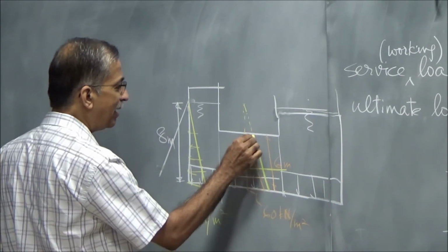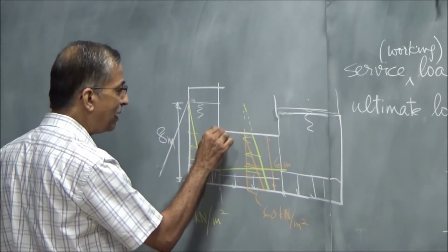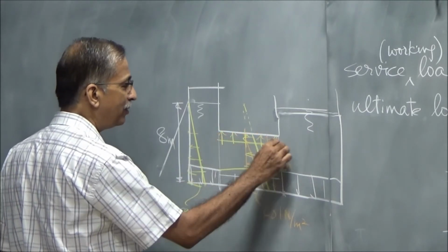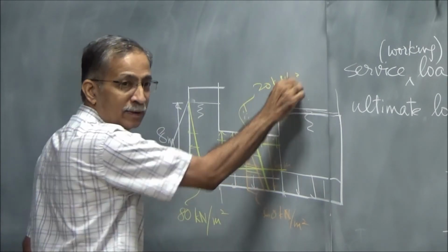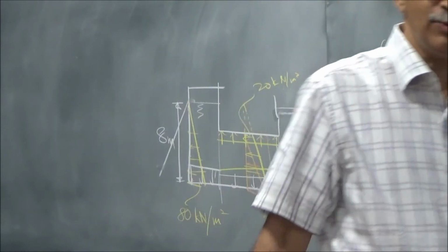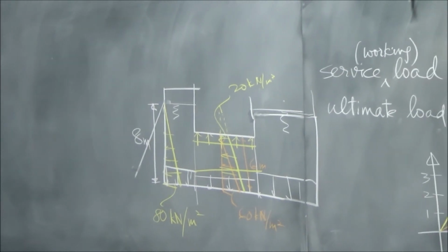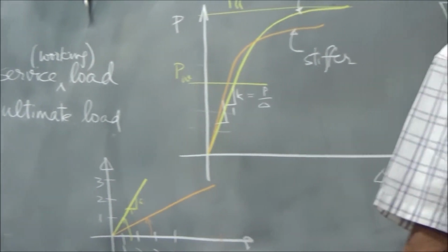And you actually end up with a pressure here, which means you have an uplift here, which was not designed for, of 20 kilonewton per meter square. So you can make serious blunders if you don't know Pascal's law. You may think that I am doing concrete building, I don't need to know Pascal's law. You need to know Pascal's law. It's fine. Serious mistakes, you'll have an uplift.